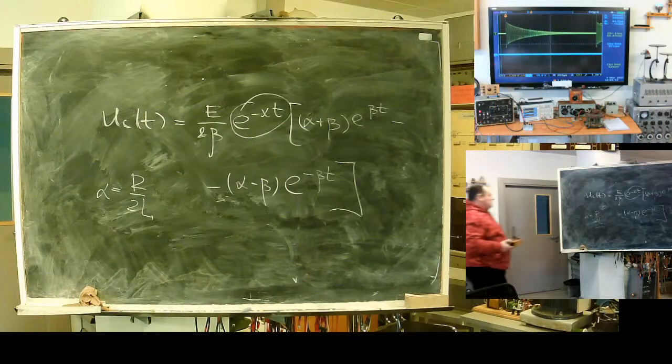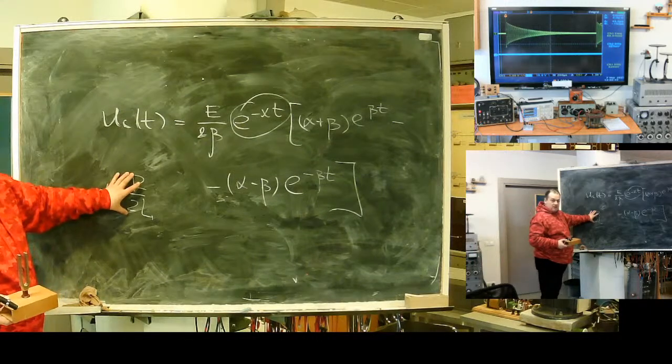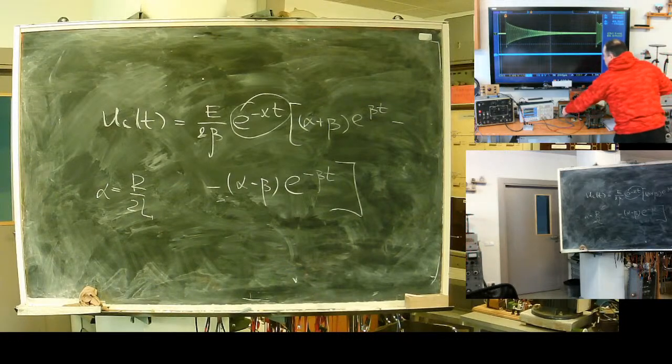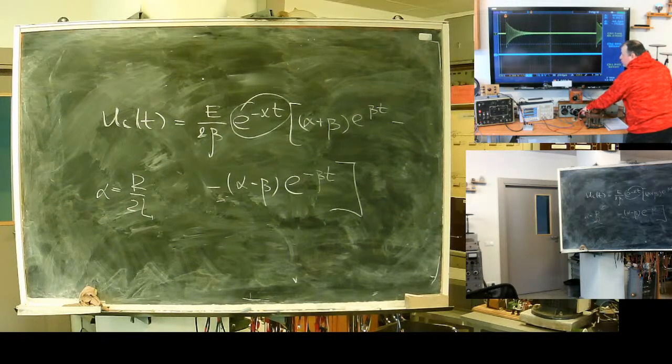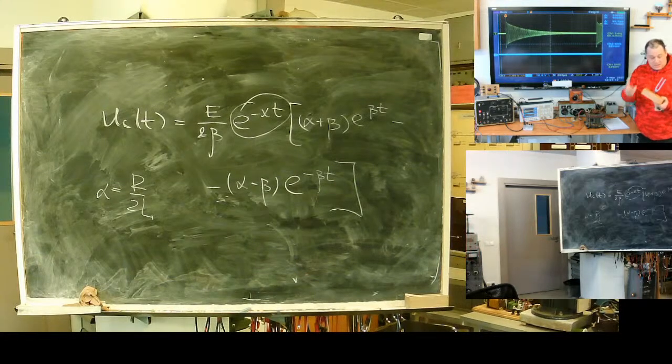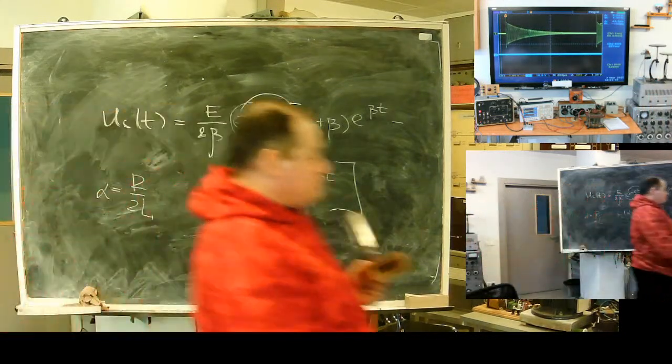And this decay is determined by the term resistance divided by double inductance. If I add more resistance, okay, it's low. See, I'm adding more resistance and we see faster decay. It's like damping. My finger is the same, it consumes energy like the resistance box.